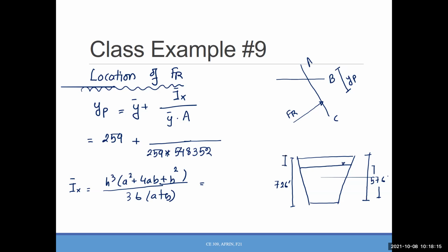That is a good question because we will discuss that in the next part. We are not doing anything from the top of the wall because when there is no water, there is no hydrostatic force. So if you draw a pressure profile from that point, that will be wrong because no water, no hydrostatic force. So we have to always start from the water surface.